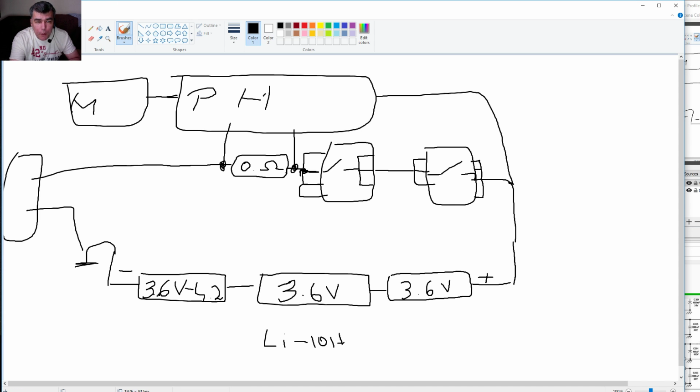Okay, so this power management chip here, what is it doing? It's controlling the battery and reading how much power goes through this resistor, yeah. And also it will shut down things if you have any short on the battery connector. It will control the charging current, and if the charging current is too high, it will cut down the power.